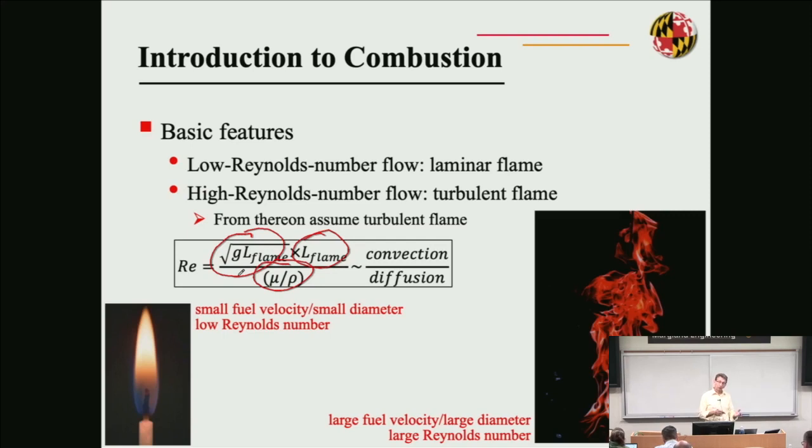In a laminar flow, you are dominated by diffusive processes. In a turbulent flow, you are dominated by convective processes. So this is not the same thing. In our fires, typically the Reynolds numbers are not that high, but they are high enough to be turbulent. So we have moderate turbulent conditions in fires, and we belong to the regime described by the picture on the right.